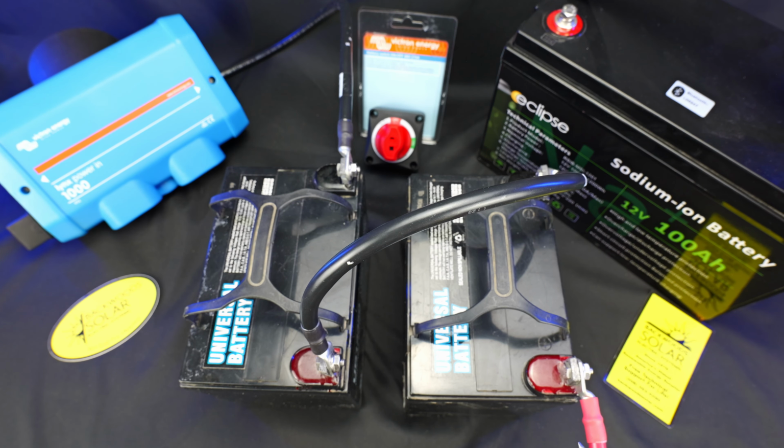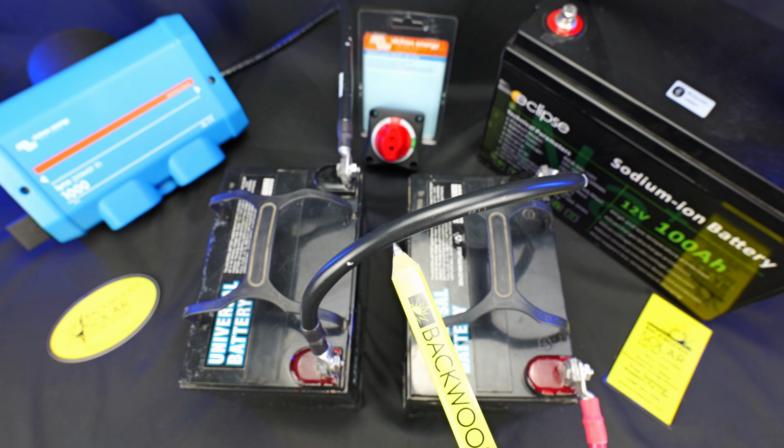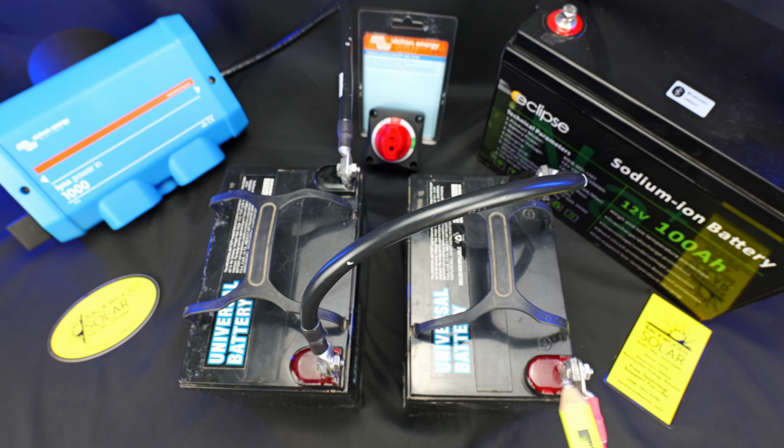And then the second note specific to lead batteries, and flooded lead acid in particular, is if we're developing any corrosion on our terminals and how to deal with that. You'll see a lot of discussion about removing that corrosion or crystal buildup. I'm not a big fan of using baking soda or any really alkaline other chemicals on my batteries.